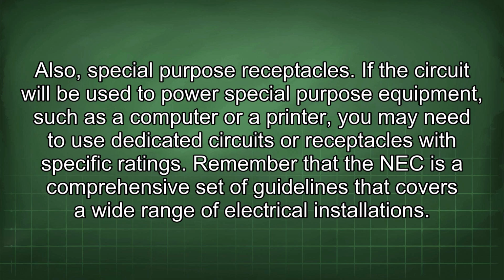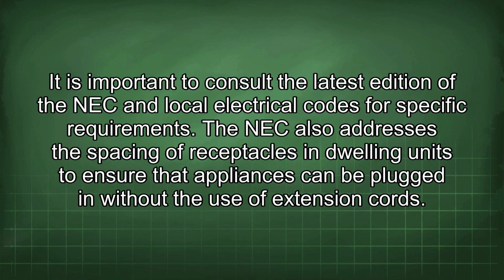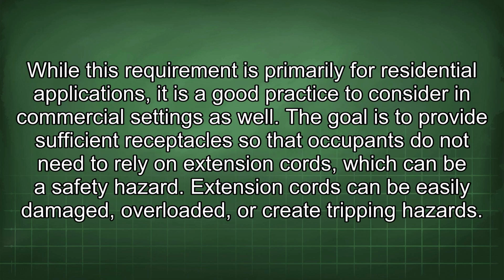Remember that the NEC is a comprehensive set of guidelines that covers a wide range of electrical installations. It is important to consult the latest edition of the NEC and local electrical codes for specific requirements. The NEC also addresses the spacing of receptacles in dwelling units to ensure that appliances can be plugged in without the use of extension cords. While this requirement is primarily for residential applications, it is a good practice to consider in commercial settings as well.